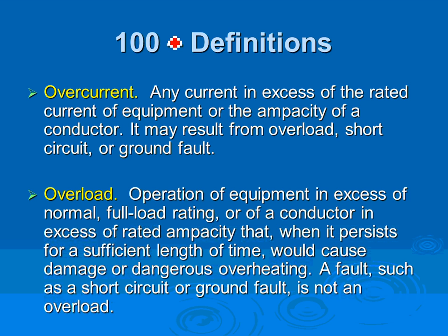So the overload is a special condition of the overcurrent. Overload is only when you overload a conductor or you overload a machine, meaning it's rated for a certain amount of amps, and you make this machine work hard enough to pull more amps than what it's rated for. Same thing for a conductor. The conductor is rated under its normal operating condition to carry 10 amps. You tie more loads at the other end and you make it operate at 15 amps.